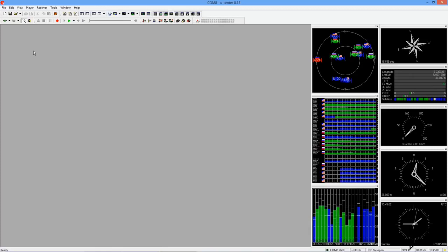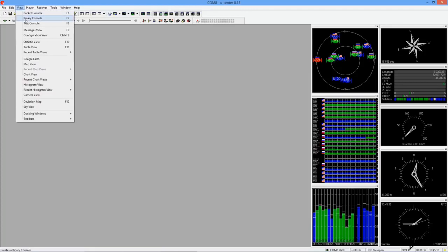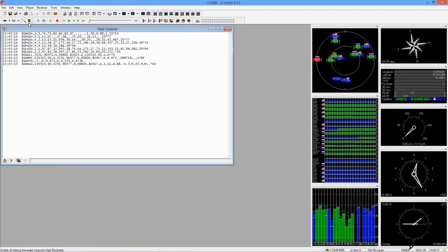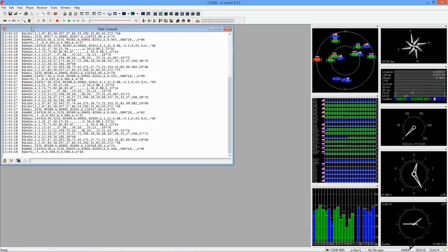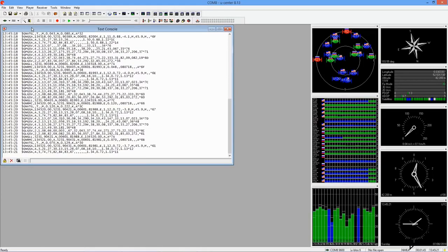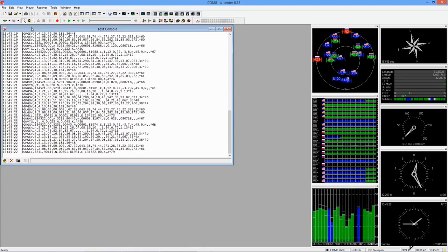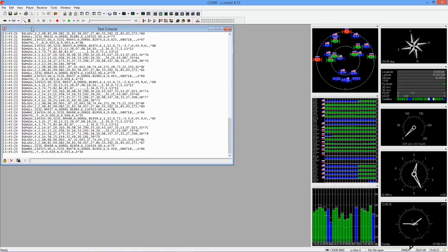Now that we know how to connect the GPS and what parameters are needed, we can start with the first part of the program. And that is the setup part. At startup, the GPS module outputs one block of data every second at 9600 baud. So the refresh rate of the latitude and longitude is 1 Hz, or once per second.